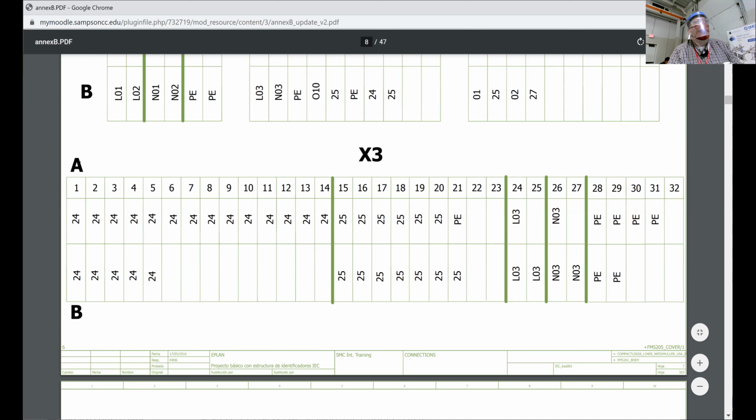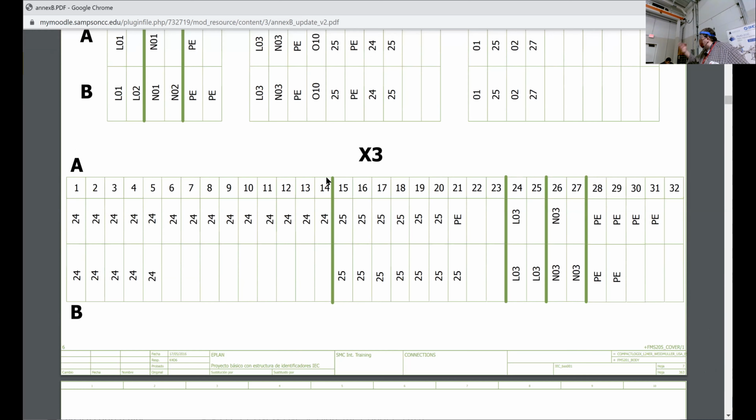They all go vertical. So X3 16A connects to X3 16B. You know what I mean? These two connect together. These two connect together. And so the A's and the B's are all hooked together. They run through. Whatever wires land into A and whatever's landing into B, they're connected through a little bus clip in there. Okay, that's built in. That makes sense? On the terminal strips.